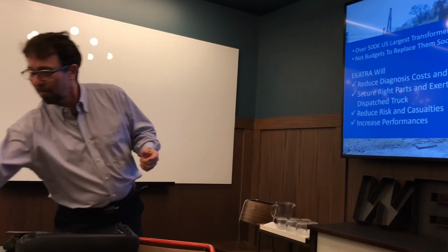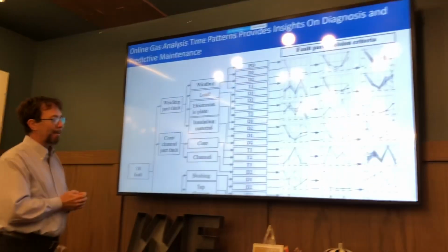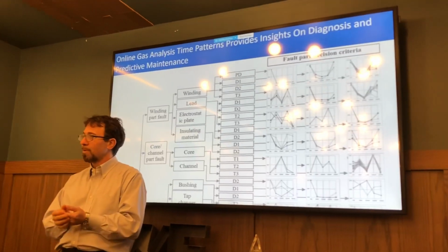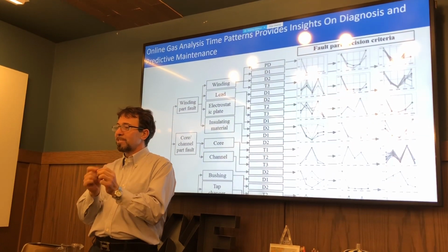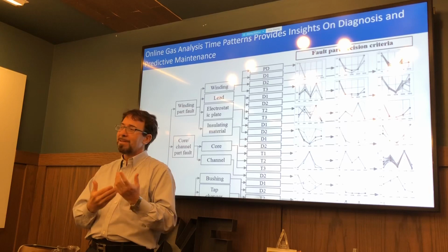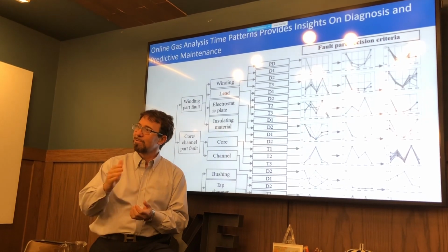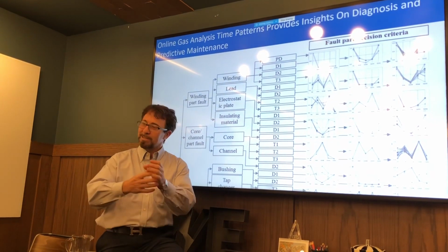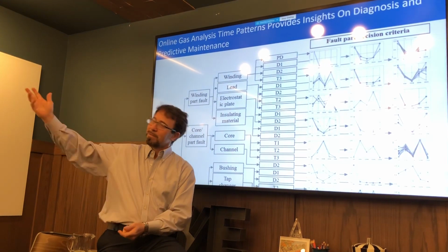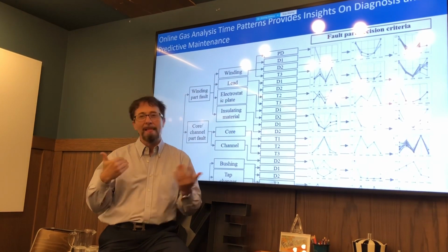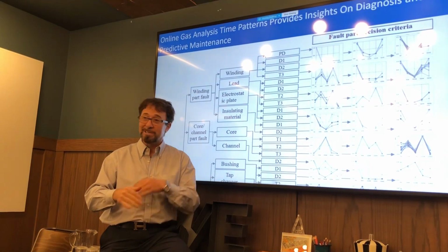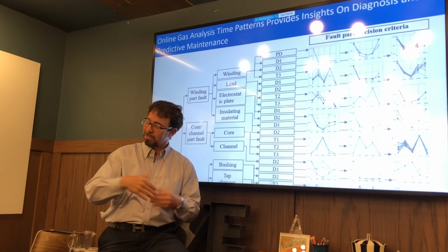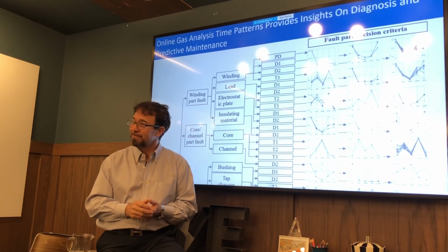In the case of oil, what generally happens is that when the winding is no longer insulated, when things are not working, the electricity creates gases. And depending on the quantity of gas, you know how soon the transformer will fail. And that's the science today. A man goes there, takes a sample, sends it to the lab, 2 or 3 days later they say, you found this gas, you have this problem, change the oil first, but also go and change this and that. And generally, from the moment the person was dispatched to when you intervene, it's months.